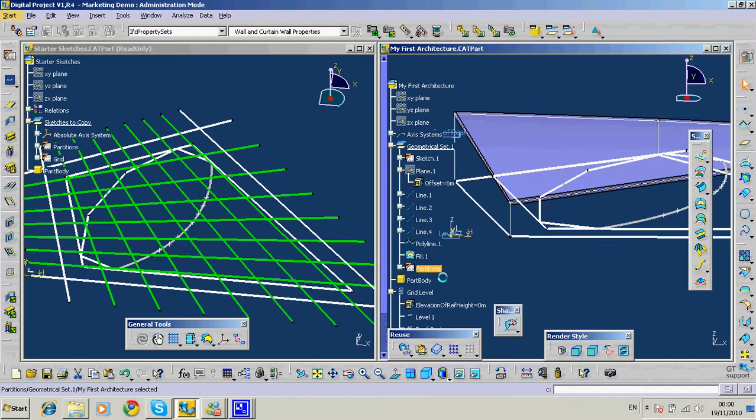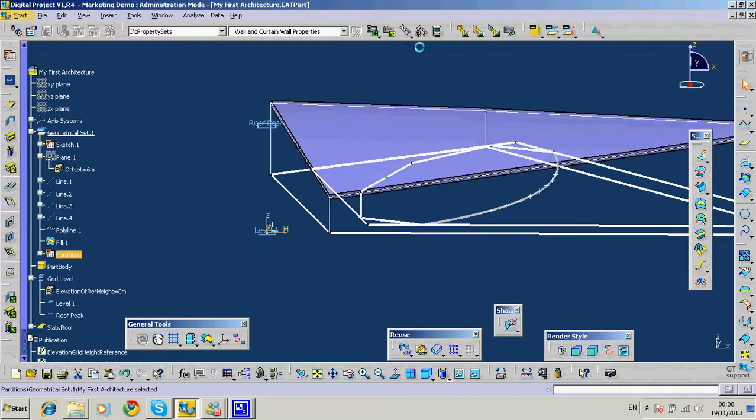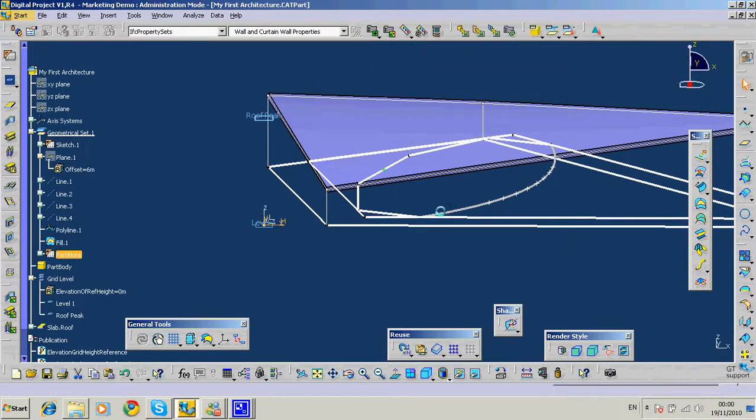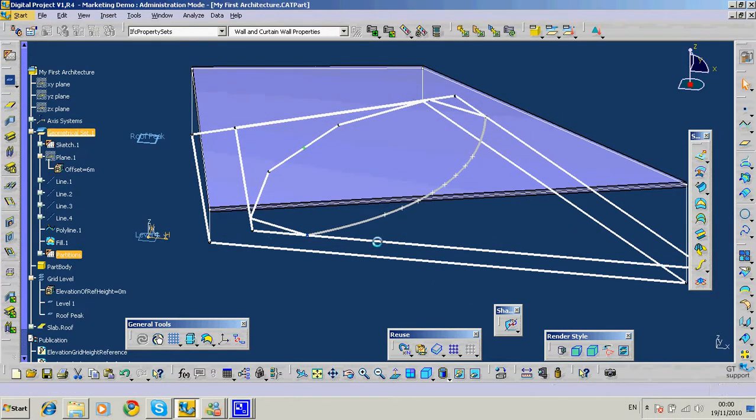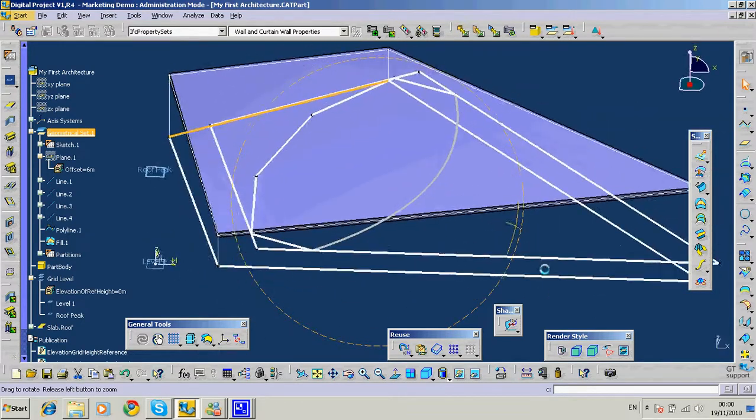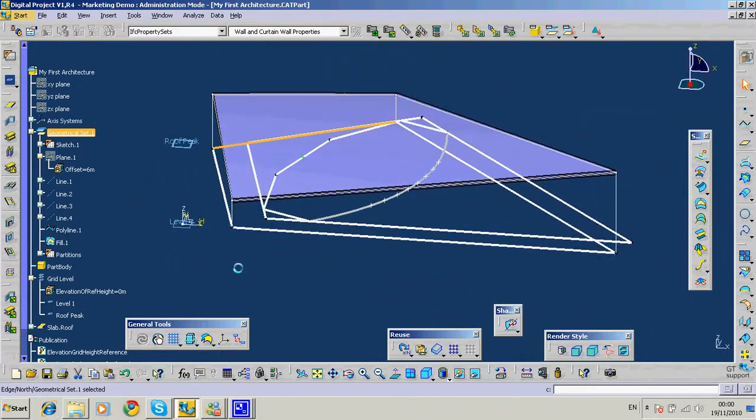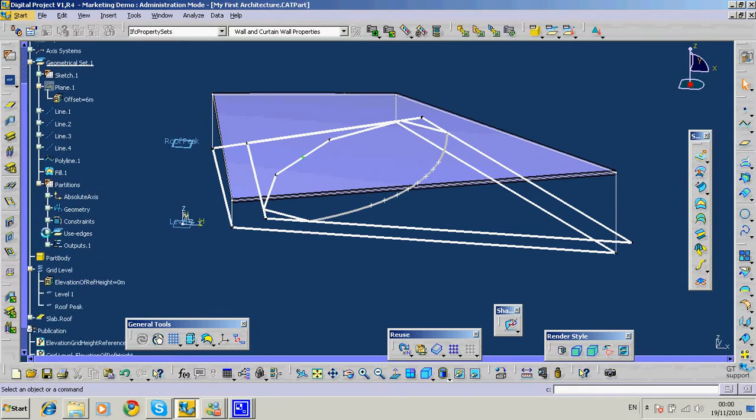Now if you do either right click or paste, or you can just do Ctrl V. So we paste in. See, that's a new sketch, and we need to align this new sketch to the roof boundary. So we say that's a partition new sketch. There are 4 elements, projection edges, currently deactivated.